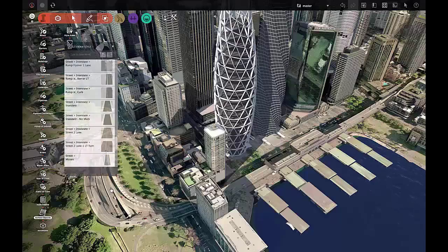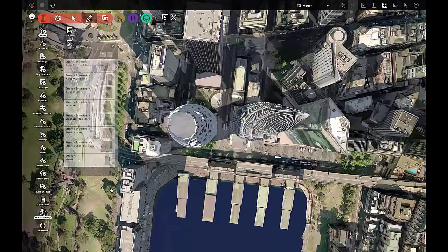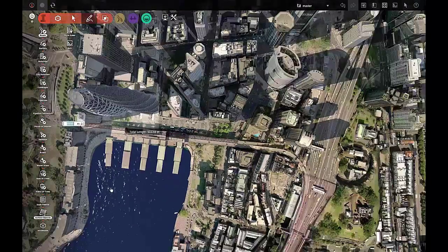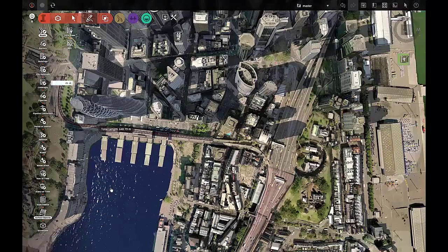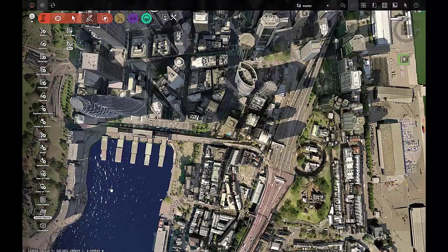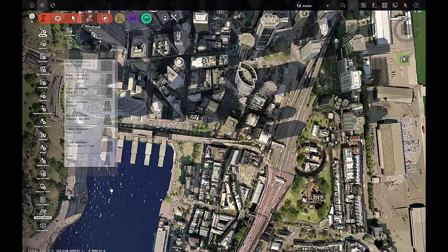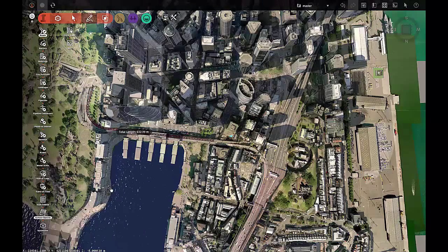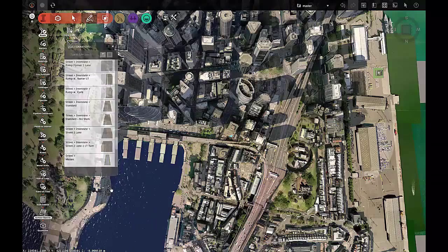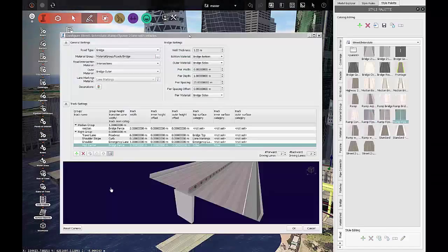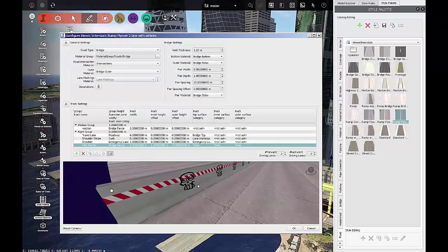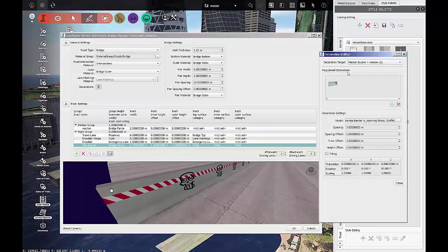But there are various ways where you can grab data from other sources, like you can bring in your Revit models, SketchUp, 3ds Max Design, Bentley models, and you can start to build up certain components using the in-product tools inside of InfraWorks. So if we look at a road design here, we can simply draw an interstate. This is the Kaho Expressway, and then we can use some of the tools inside of InfraWorks to start customizing that design of the road.